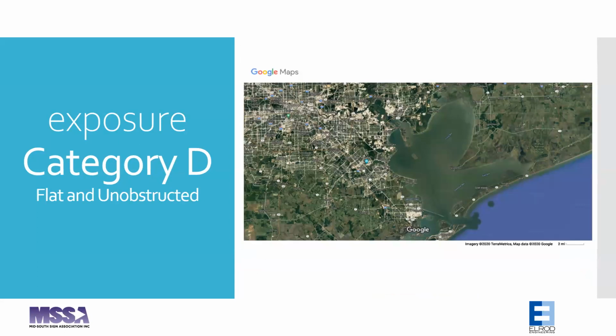And in the other direction, exposure category D increases the wind loads that are applied. Basically, exposure D conditions are on the edge of large flat areas and extend downward from that. Other than coastlines, it isn't terribly common, though you could run into this in the Midwest, and we've seen it several times in New Orleans based on the orientation of the site to the Mississippi River.